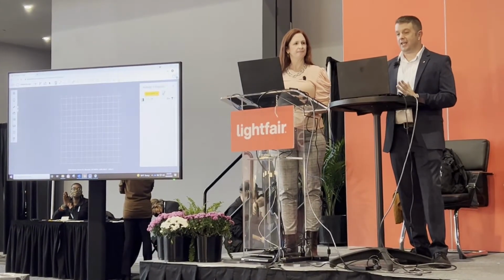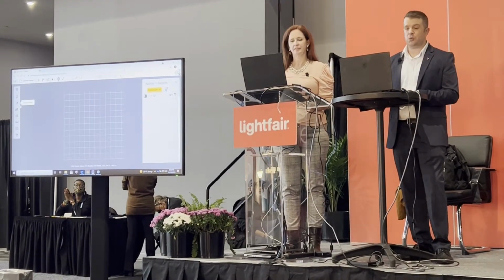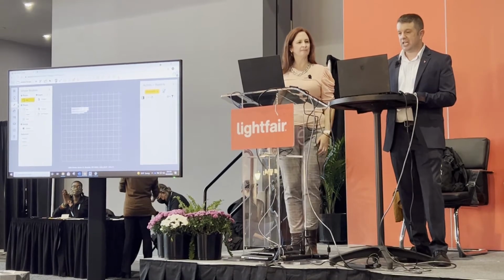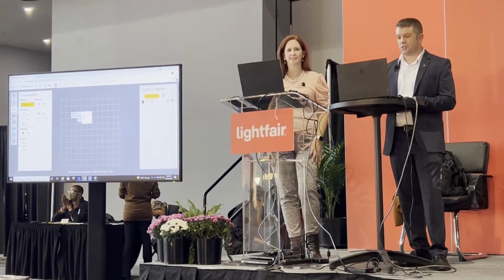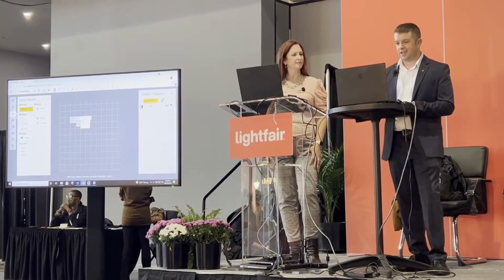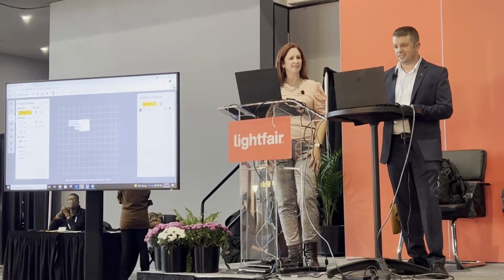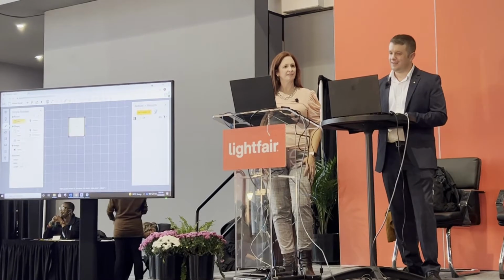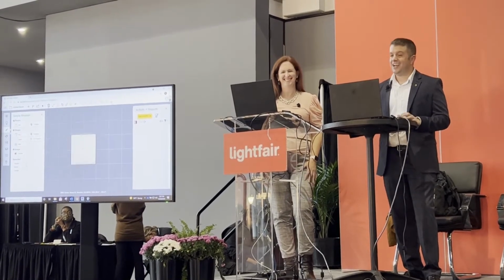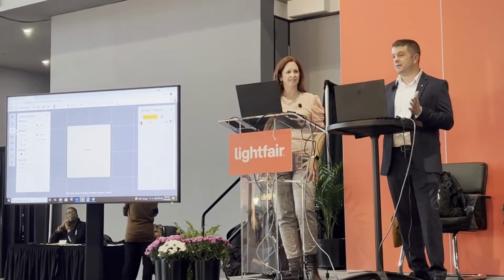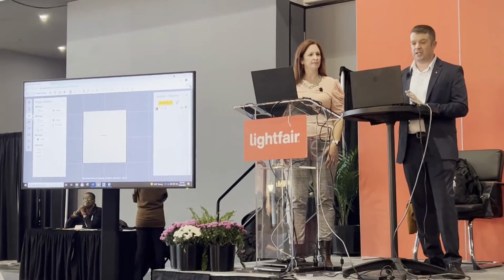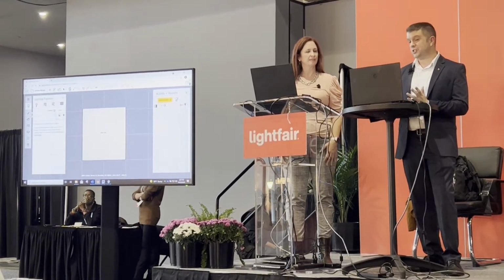I'm going to go here to my lighting plan view. We talked about a 20 by 20 foot room. I'm going to go here, Simple Room Modeler, pick a box. Draw it anywhere over here, go down to 20 by 20. Hey, probably have to zoom in. Close enough. All right, so you can see LightStanza already put in my calc grids. I put them in at 30 inches. I can change that at any point, but I don't have any light fixtures in here, right?